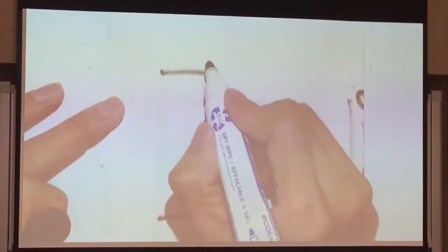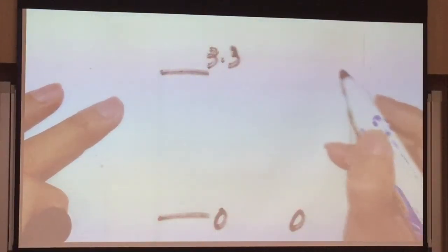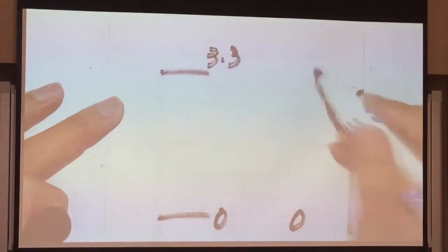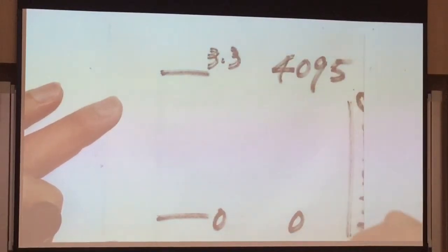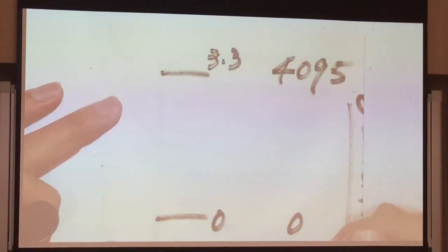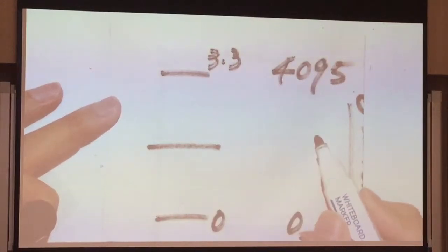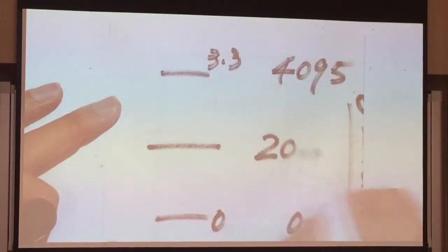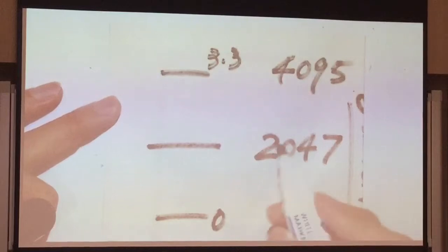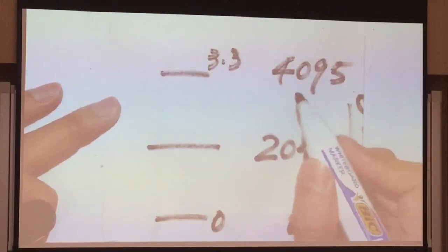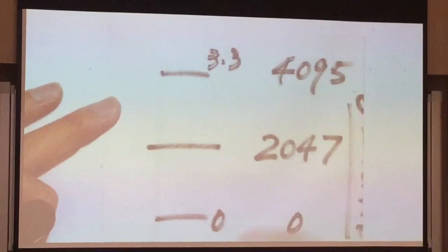When the voltage level is 3.3, you will get 4095. That's the maximum value you can get. Whenever you get a value from the analogRead function and want to find out the exact voltage value, you have to do a translation.